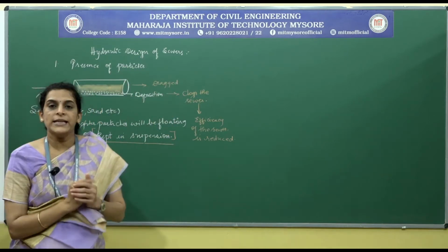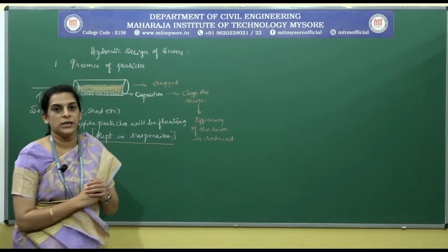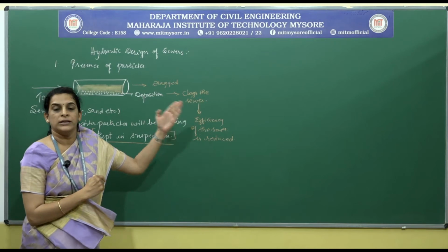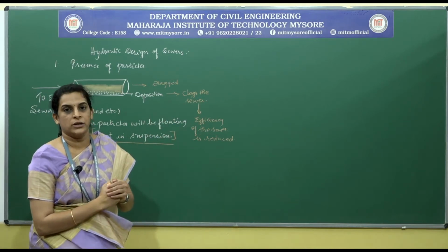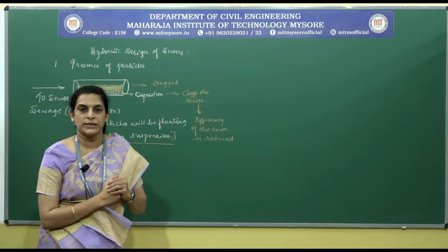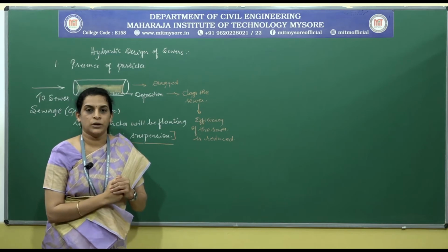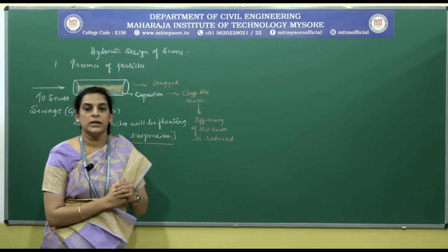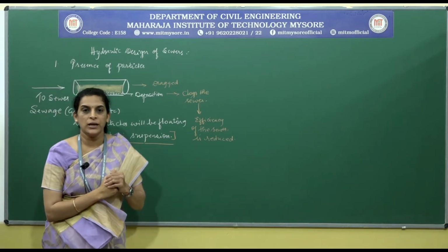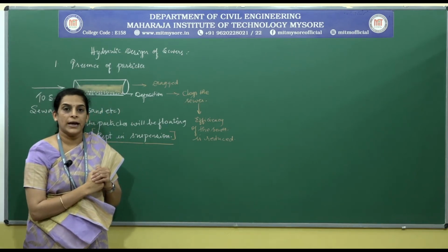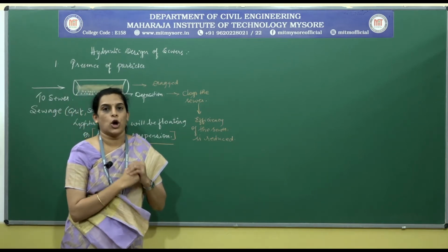So it is the minimum velocity which keeps the particles moving during the flow such that they are not deposited on the inner surface, and that minimum velocity is known as self-cleansing velocity. Otherwise, the quality of the sewer material deteriorates, making it more prone to abrasion and clogging.